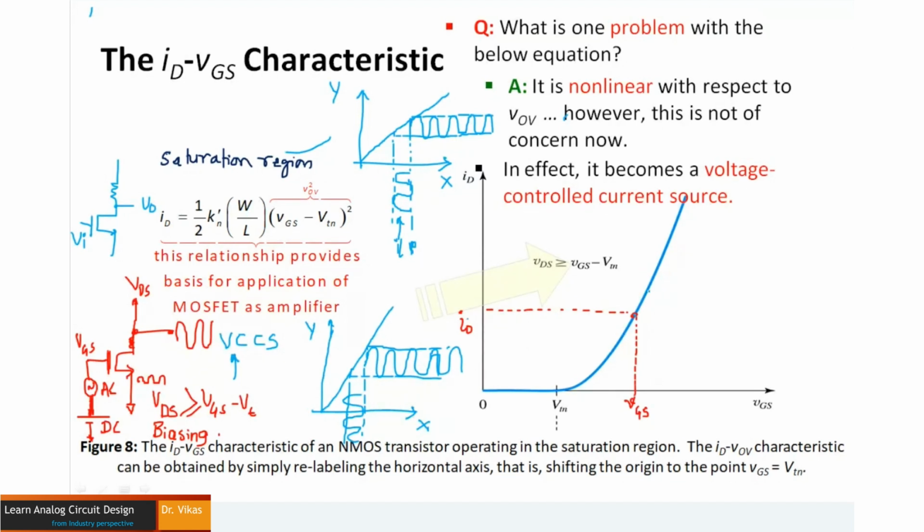I'm also going to change my voltage to the next level. Let's say that now I'm going to give the next level of VGS. I'm going to observe another current, multiply that current with the resistance, and finally I'll be able to see another voltage.